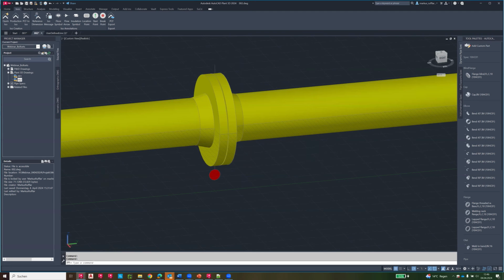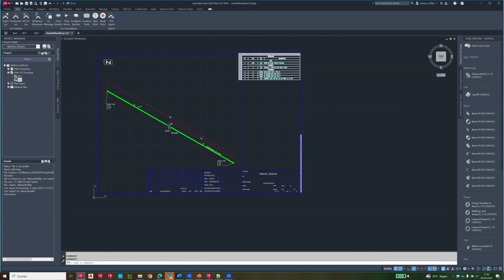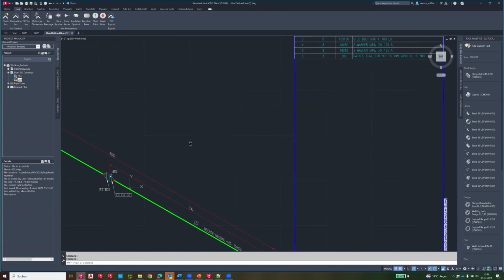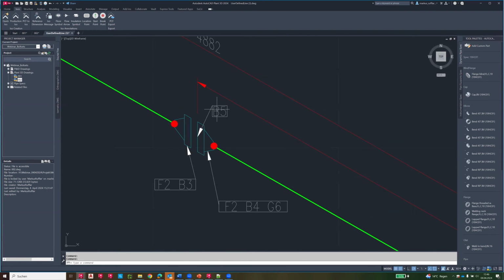And may I ask a question, Marcus? Yeah, of course. And it appears with the letter B in the isometrics when you make them separated, because now as I see, all appear as B1, for example, or B2. Yeah. Still, could we separate it with bolts B, and washer with W? This is also possible, yeah. Okay. You can switch this prefix. Can you also change it through the isoconfig XML file? This is not an issue.